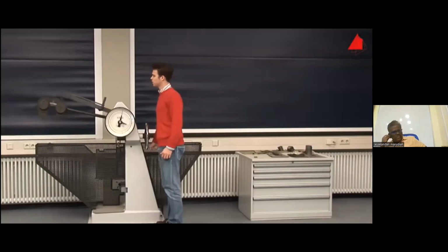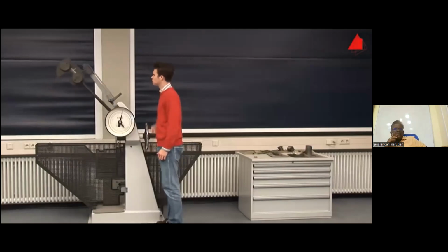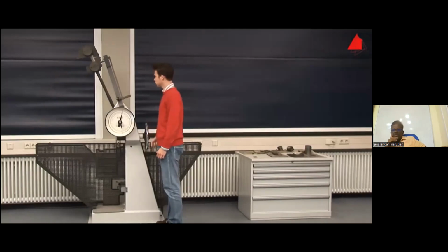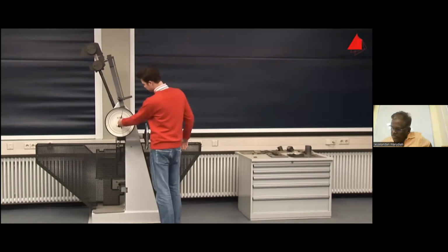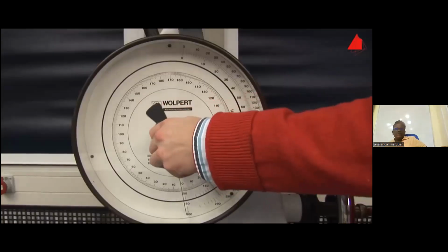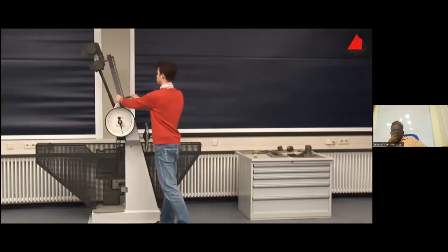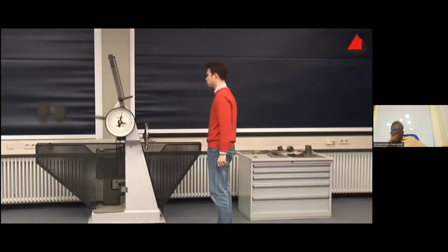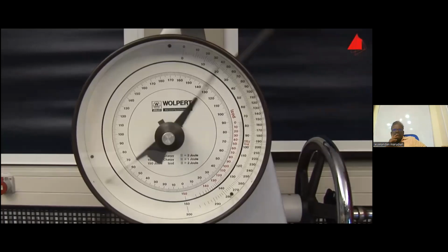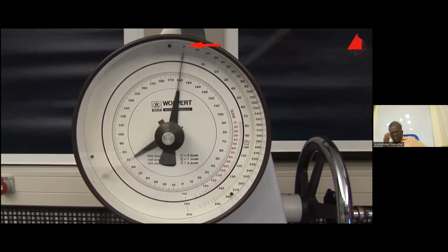This is lifted into the starting position in step 1. Then the tester checks whether the testing machine has been adjusted accurately. In order to do this, he turns the drag indicator downwards and releases the pendulum without a test specimen. The drag indicator stops at position 0. This proves that the pendulum has the correct starting position and that the friction is correctly compensated. The machine is ready for the tests.